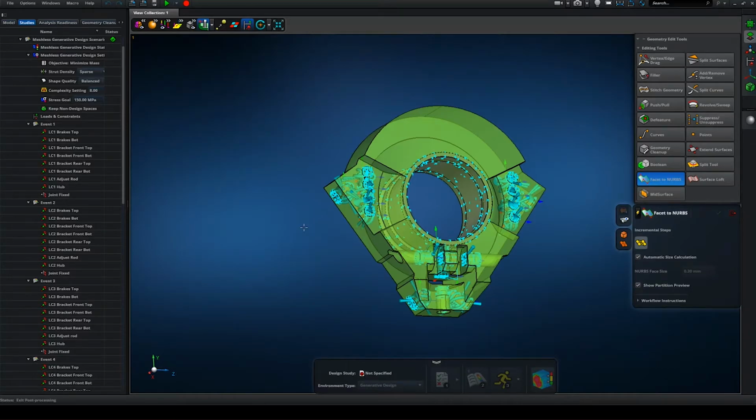Right. So first of all, it's important to understand that the technologies are different. When you do a solid finite element structural analysis, that's as accurate as you can get. The technology used in generative design is similar to voxel meshing technologies. So there is a difference in the actual stress result.